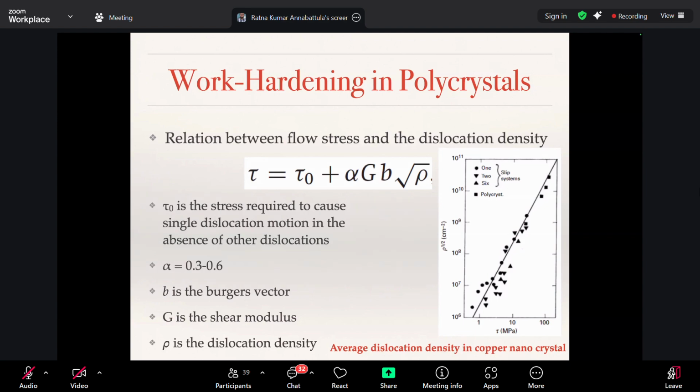In grain size, you can have a single material. It need not have another material. Even if it is pure copper, because you have more grains, the dislocations come and interact with the grain boundary. But in solid solution strengthening, it can be a single grain, but it has two materials, because the second material has a different sized atom.